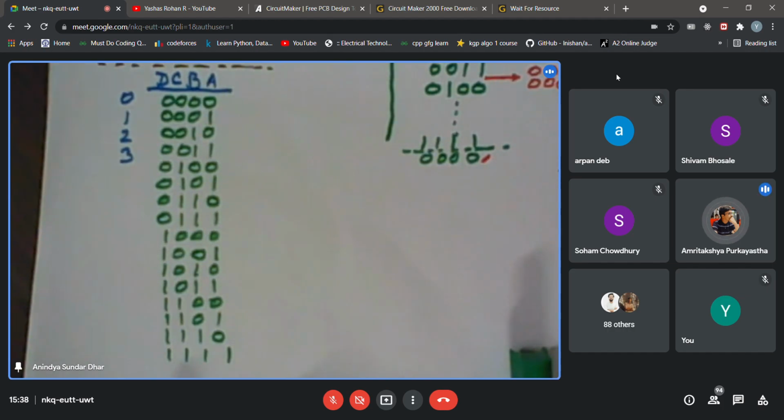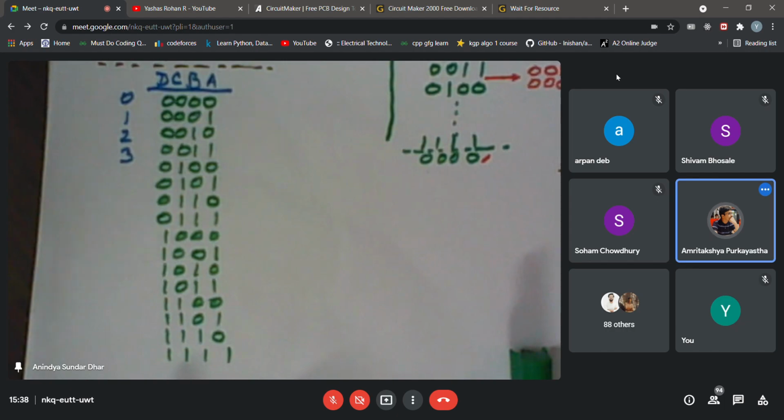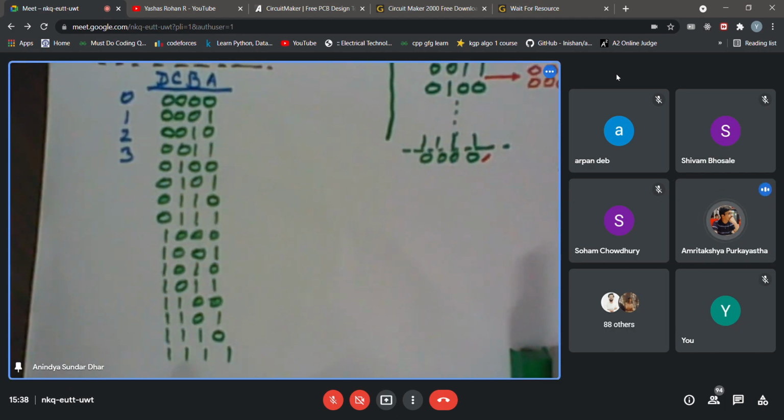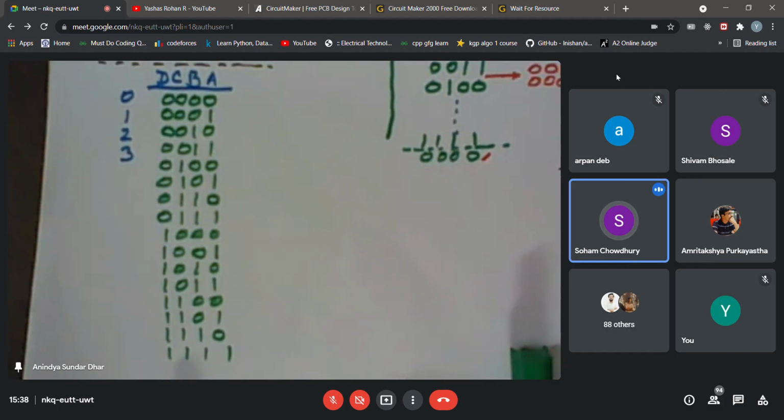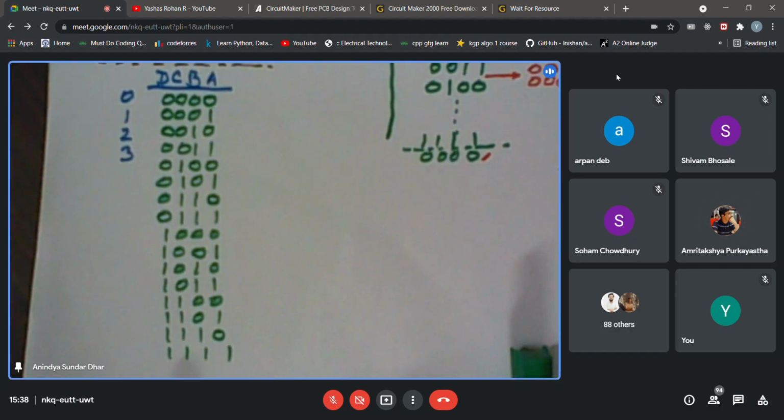But other than that, can anyone suggest any other solution? You can use the rising edge of the C. No, but there is a simpler solution. When we say mod 4 counter, how many bit output do I expect when it is having a state of 2-bit? 2 is enough. 2 bit only? Right. So I can simply ignore that C and D.